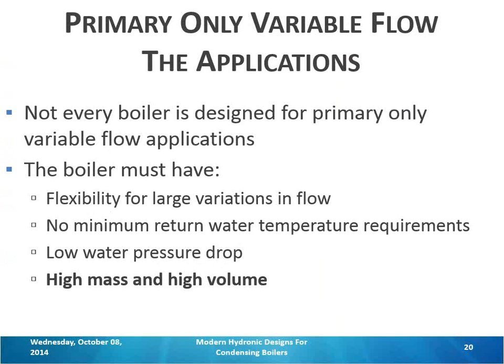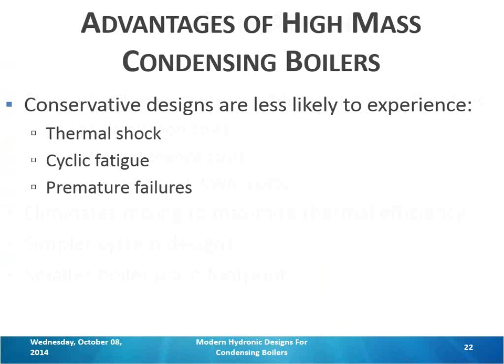And what are advantages of this type of design, of primary only? Well, we eliminate all the boiler pumps. We eliminate all the piping and some of the controls headache that goes along with mixing temperatures. So if you're a consulting engineer or a designer, it makes your life a lot easier. If you're a mechanical contractor, you have a lot less to install. You don't have to weld all these additional T's and put in check valves, strainers, and pumps.